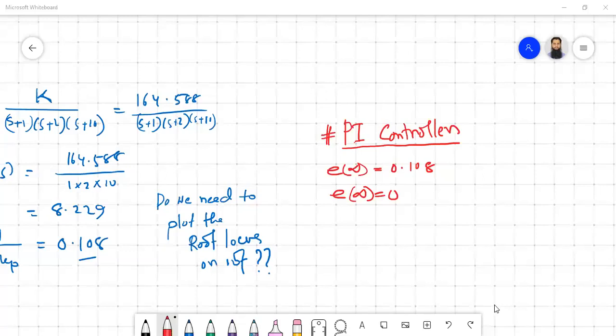Okay, so we start with example 9.1. As we were just saying about the uncompensated portion, we already discussed that and figured out the steady state error of the uncompensated system. What we want is zero steady state error, and for that we need active components, an ideal compensator or PI controller. And this portion is arbitrarily selected.